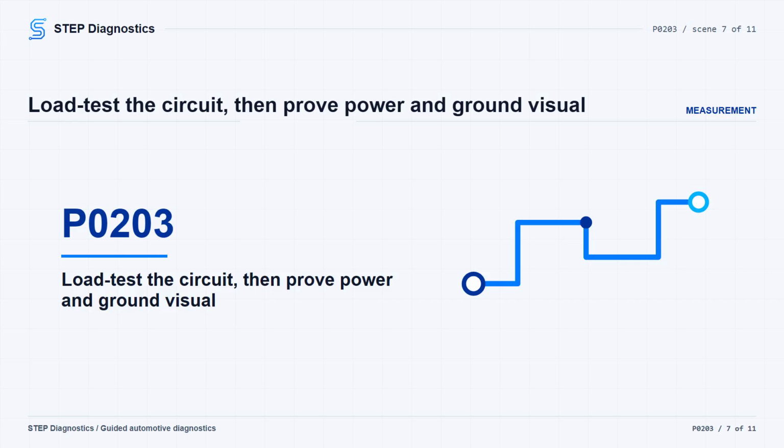Most small diameter 18 gauge and smaller wires are expected to have less than 2 ohms, and most wiring harness circuits are also expected to have less than 2 ohms. A standard DMM ohm meter's low resistance resolution, approximately 0.1 ohm, limits its accurate use to circuits carrying less than approximately 5 amperes. If reversing the DMM leads changes the resistance reading and the circuit does not contain a semiconductor, treat that resistance test as invalid.